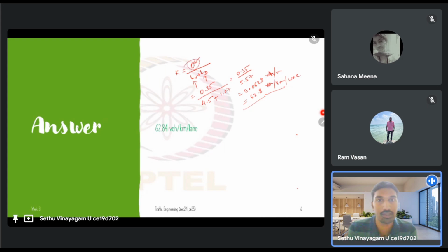This occupancy is coming from a given location on the road, right? We have installed this loop detector and then measure the time the vehicles are present within this loop detector in a given time period. So this is much easier, right? That's why we go for getting the occupancy and then deriving the density out of it. So that's why we do this. Okay, any questions?